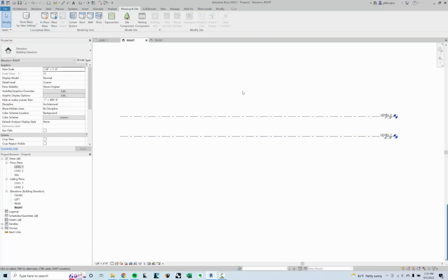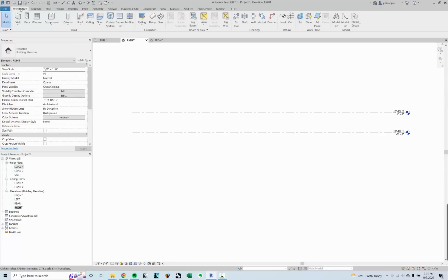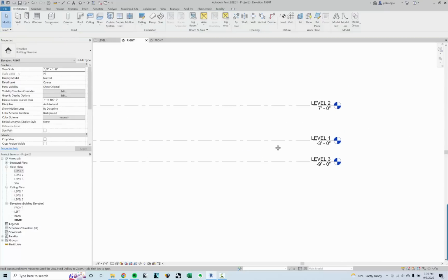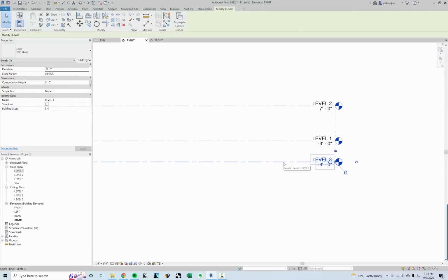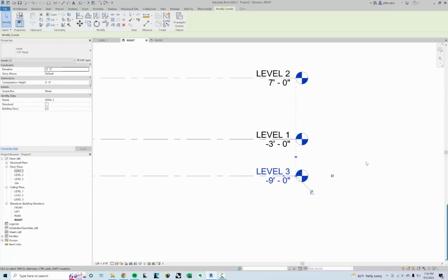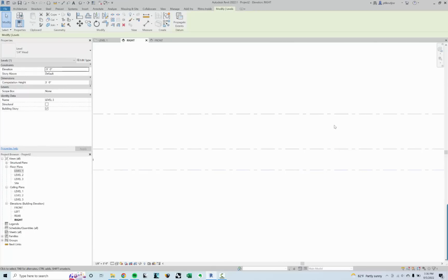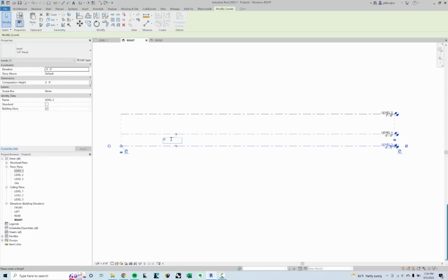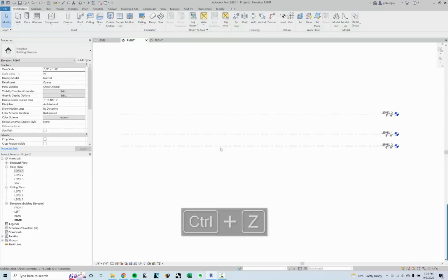This will be the base of the pavilion. So I'm going to go into architecture and then level, and I'm going to come here and click and drag this. It's 9 feet below that. That is too deep. I think it's about 3 we'll start with. So I'm going to click here, and there's a few ways I can change the dimension between them, but I can come here and say actually 3 feet, and it'll move up.